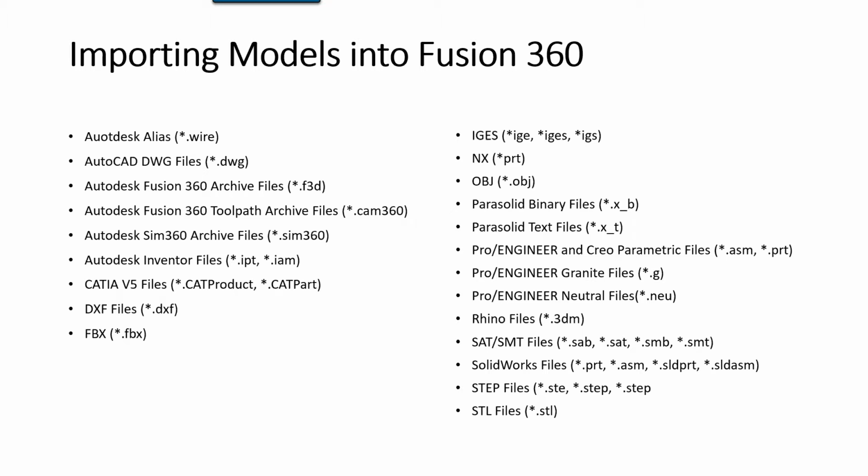Like I said, being that we're talking about 3D printing, a common question that I've gotten is, can you import toolpath files? The answer is no. Fusion 360 can't read the toolpath, and it can't create essentially a model from the toolpaths that you have generated. So just keep that in mind as we're moving forward. You have to import some sort of a solid or some sort of surface bodies in order for the software to actually be able to 3D print that at the end there.